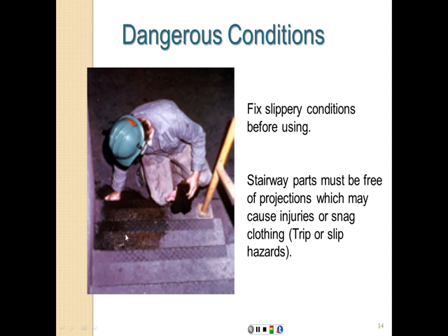If you have any oils or any grease or any slippery material, you have to fix that before someone uses these stairs, because again, if someone slips, that might lead to a fall, causing some injuries. So fix slippery conditions before using. Stairway parts must be free of projections which may cause injuries or snag clothing, trip or slip hazards.